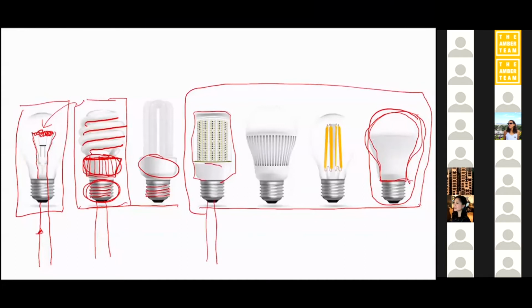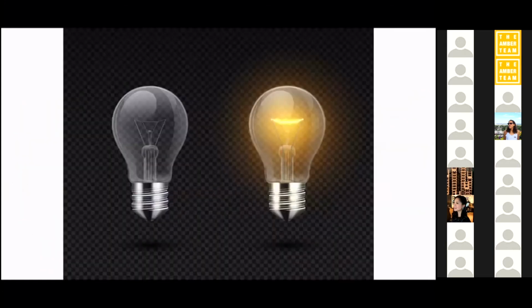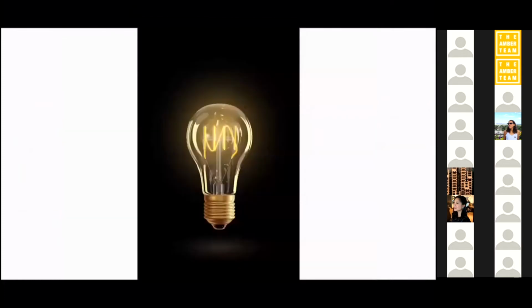Now, these use a piece of equipment called the driver, which is pretty much like a ballast as far as we're concerned. As far as an engineer is concerned, there's different technology, but these use a driver, and the driver again kind of converts the alternating current into whatever that particular LED wants to produce that particular color of light and so forth. So we can dim these fairly easily as well, and we can go beyond all off and all on mode, and we can dim it.